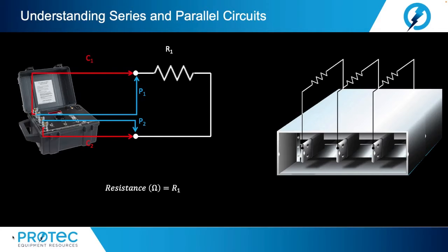And then the voltage drop, or the potential, is also a measured value. So the measurement becomes independent of lead lengths, connection types, etc. Since we're always dealing with measured values, we're always going to obtain the most accurate measurement of the actual resistance or specimen that we are interested in, regardless of lead or connection style.